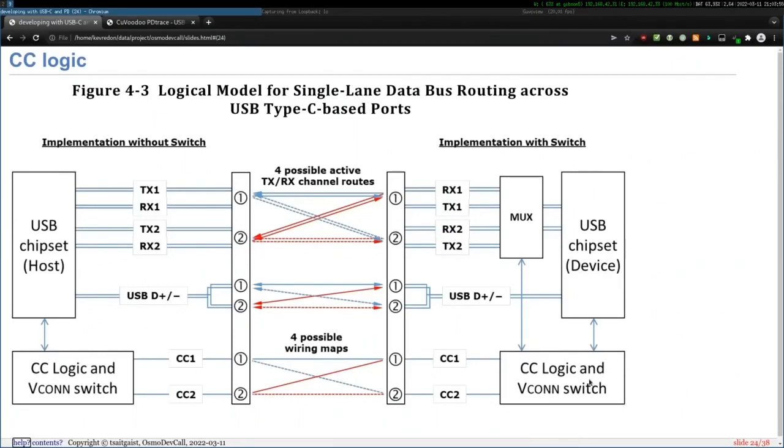So this is proprietary. It is huge. It takes a lot of space in the flash. So be aware, if you want to talk power delivery, take a chip with a bit more flash than you would think, because most of the vendors provide a large firmware. I don't use the one provided by the power delivery controller.